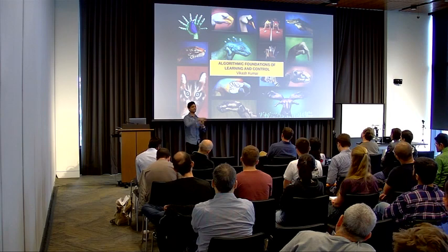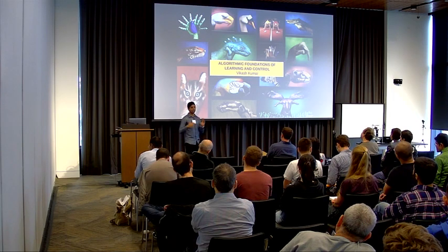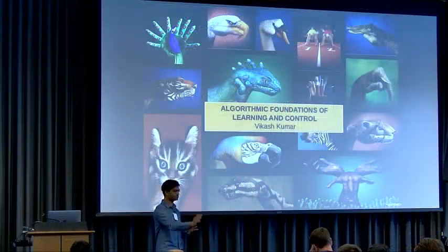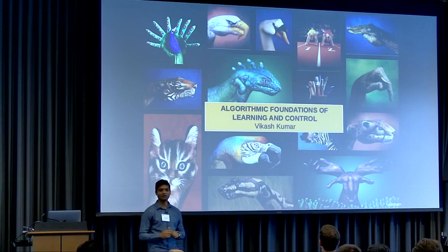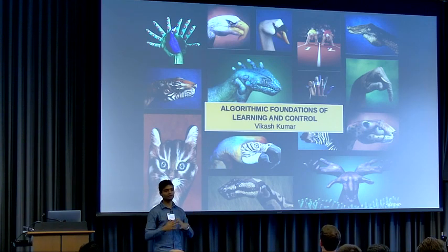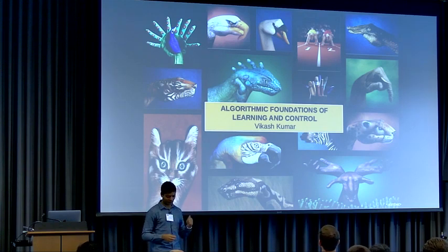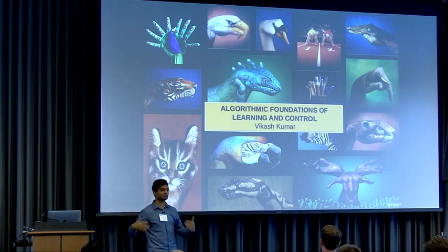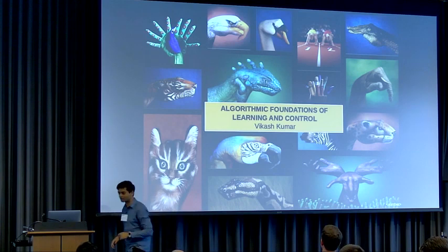Some of the differences in the applications will be that these are really high-dimensional systems where you cannot form any kind of simulator, much like what Byron was mentioning. We are talking about dimensionality roughly between 60 to 100 dimensional spaces with a lot of deformation. There is no rigid body assumption that is probably valid over there. And the second thing I want to also point out is the state distribution shifts quite a bit. So unlike Byron, where you're going on the track, here you can't really visit the same place again, almost.